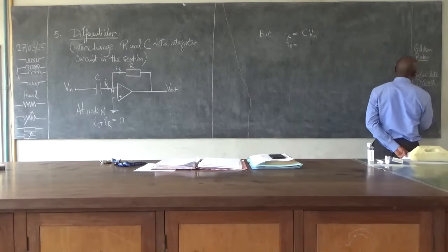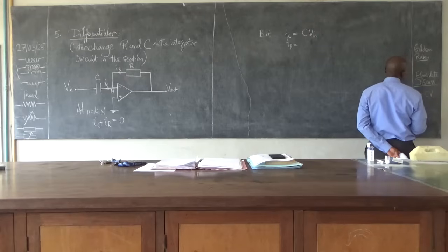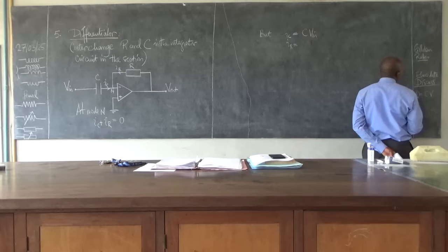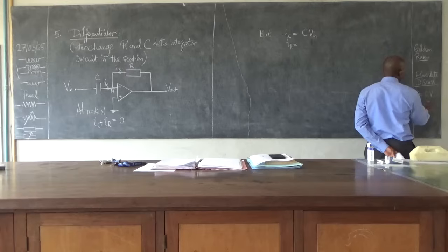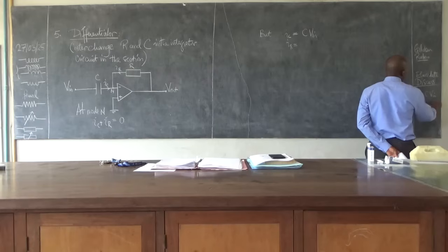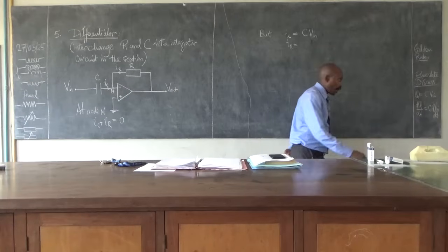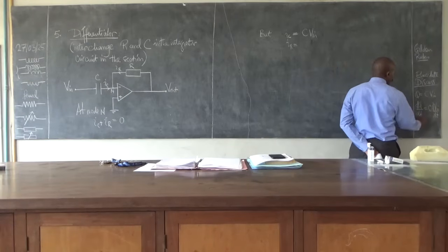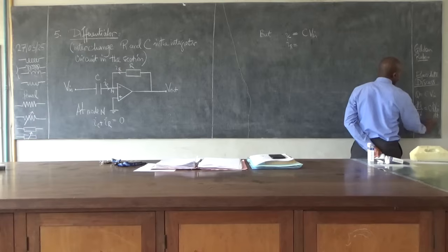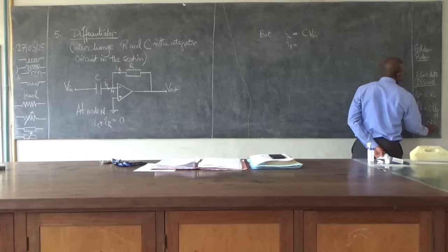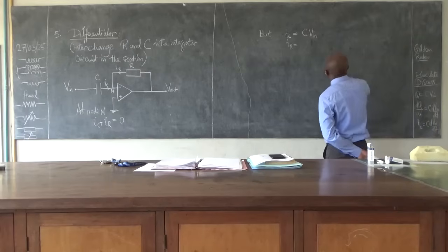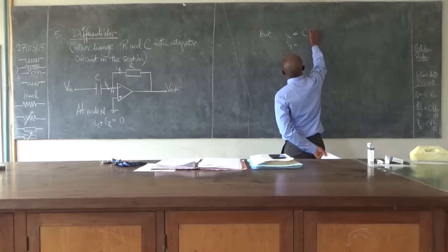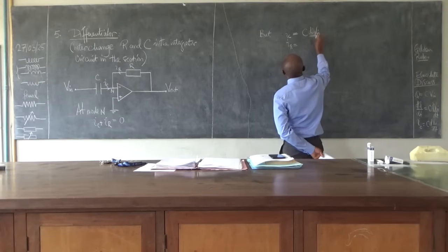Okay, so we have Q is equal to CV. I is equal to dQ/dt, okay, this is V in. dQ/dt will be equal to C dVin/dt. So the current through this would be equal to C dVin/dt. I was forgetting the d/dt. Yes. Okay, thank you.